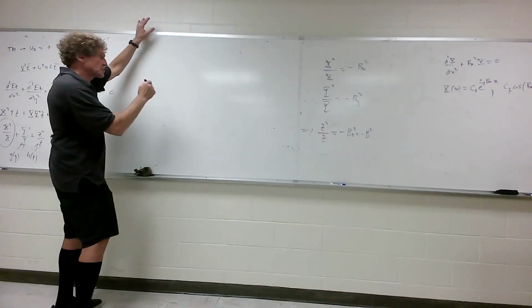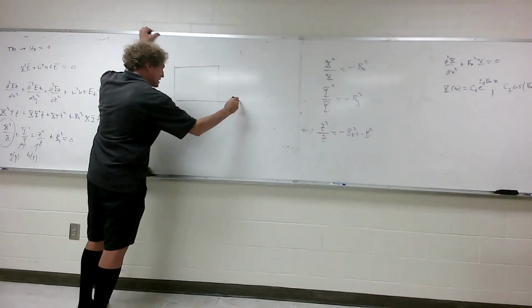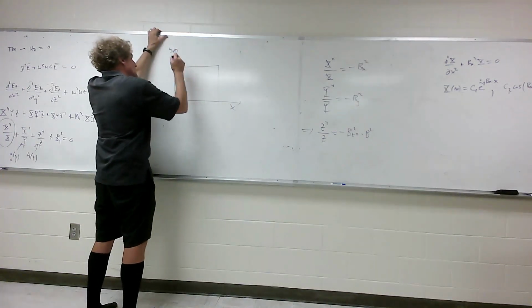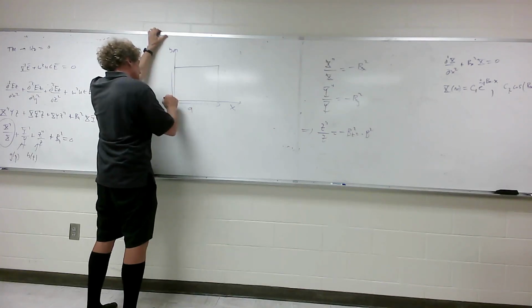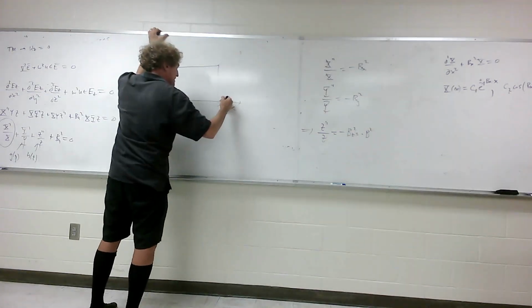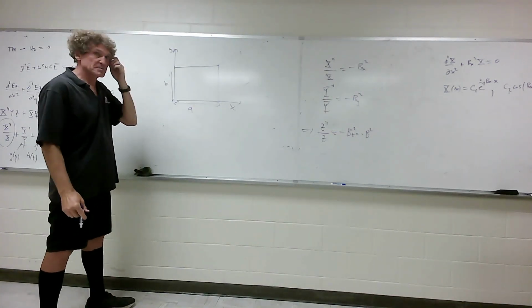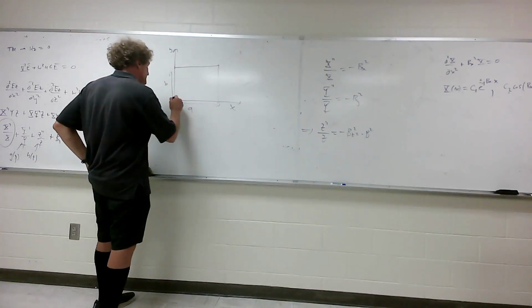So I'm going to just go down the cross section of the guide, like so. Here, that's x. Here, that's y. The guide has a width a and a height b. And really it goes this way. And basically, the wave is confined in this direction, but we only have an Ez. You with me? Now, Ez is going in this direction, right?